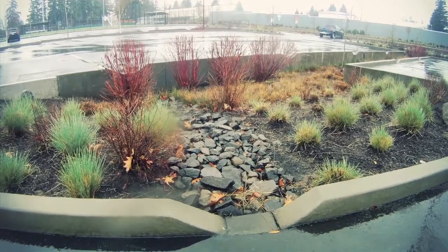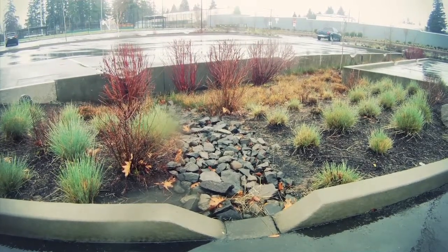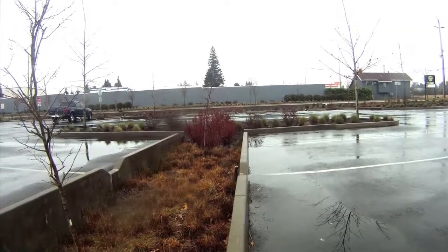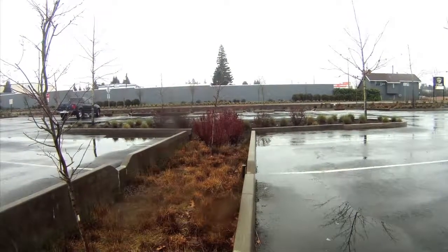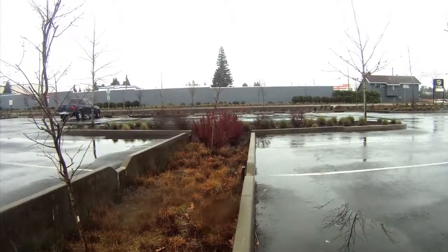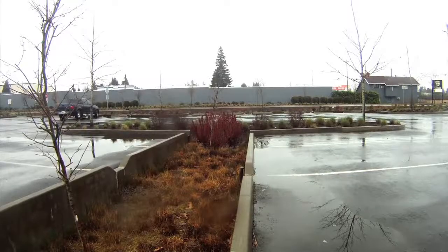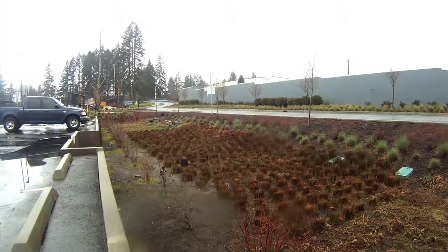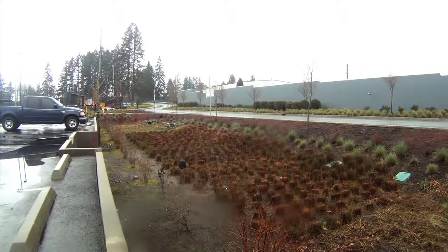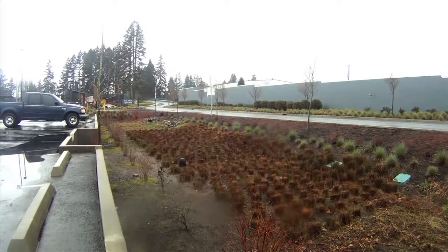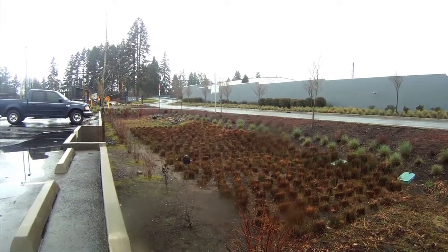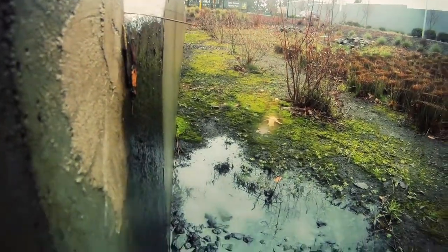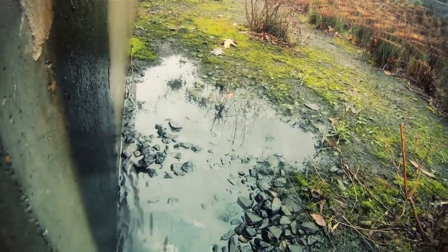Bioretention utilizes soils and both woody and herbaceous plants to remove pollutants from stormwater runoff. Rain gardens are a widely used bioretention design strategy. Bioretention typically treats stormwater that has run over impervious surfaces at commercial, residential, and industrial areas.